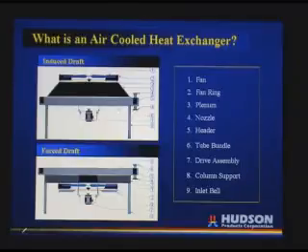The other option is a fan with a spacing between the tubes to allow a shaft to go through up to the top of the bundle, and then the fan is on the top, and it basically pulls the air up from the bottom through the fan. There's an additional discussion as to why that is a preferred design for applications where you have a large number of multiple bays.